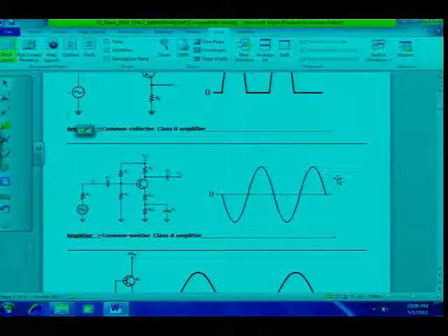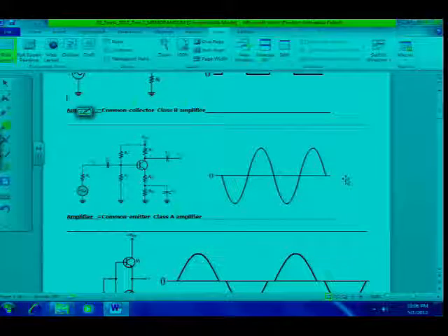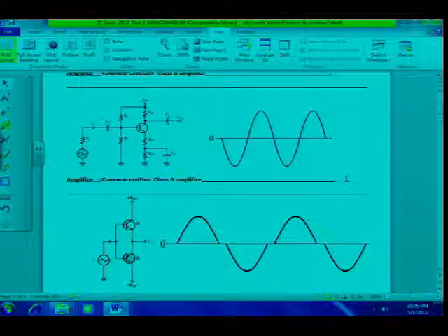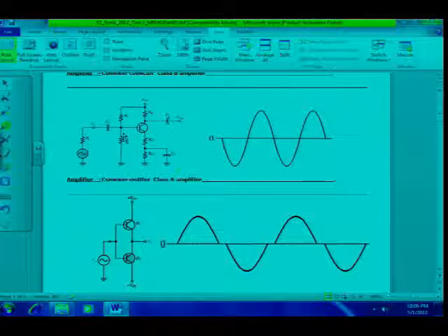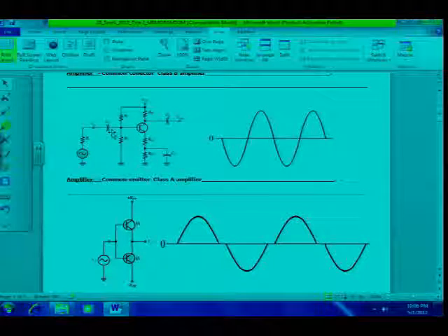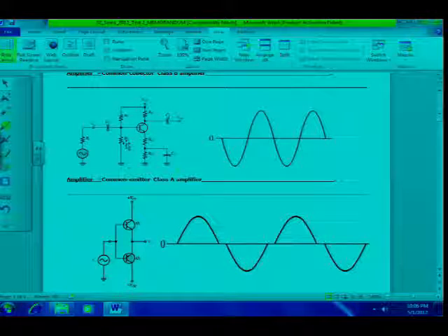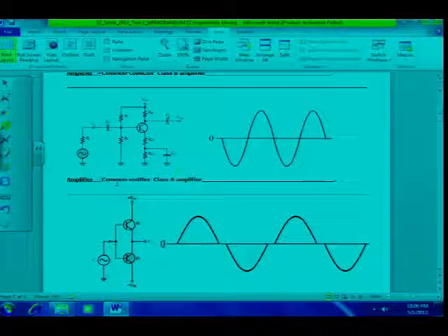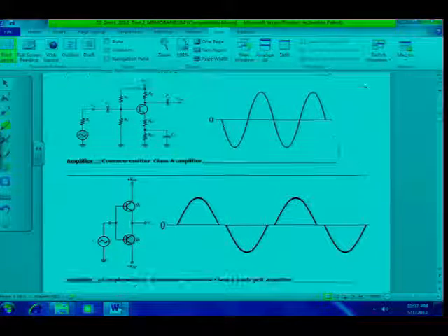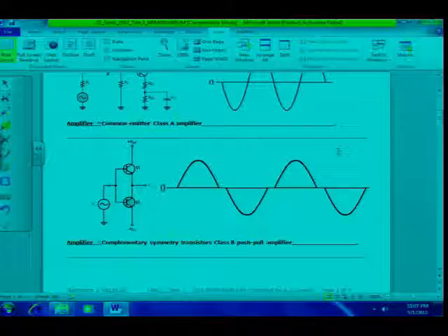Alright, the second one, the amplifier that we started off this semester, common emitter. If I look at the input and the output, and I can see it's biased, it's voltage divider biased, so in this case it's most probably a class A amplifier, linear amplifier, and I can see my 2 waves on the output shown there. So a replica of the input signal, only it is amplified.